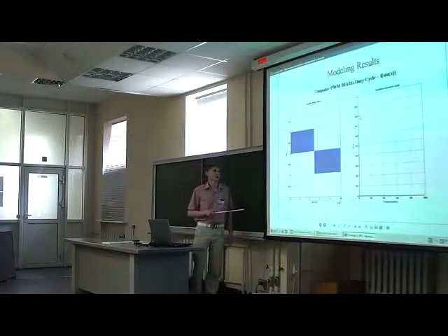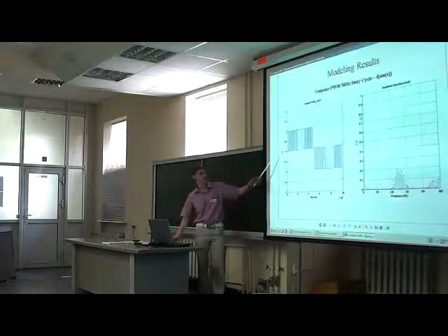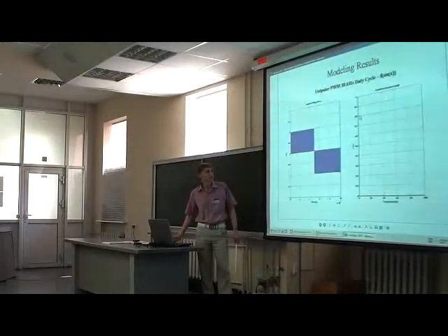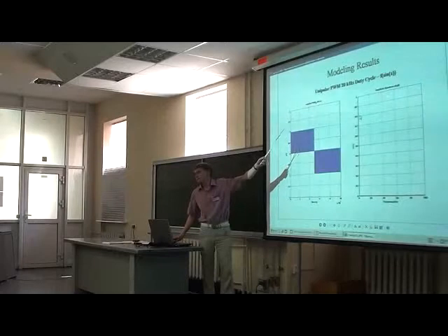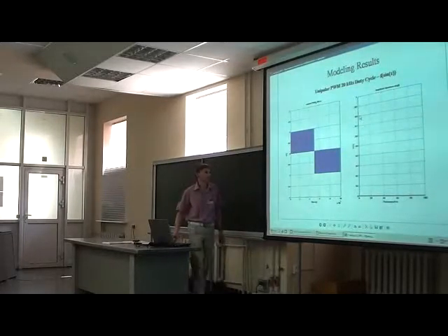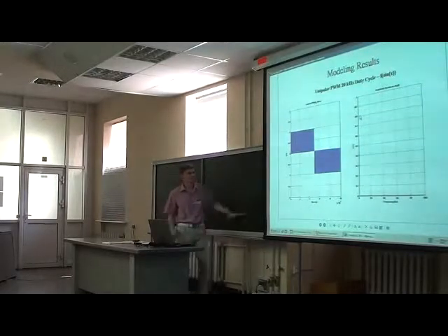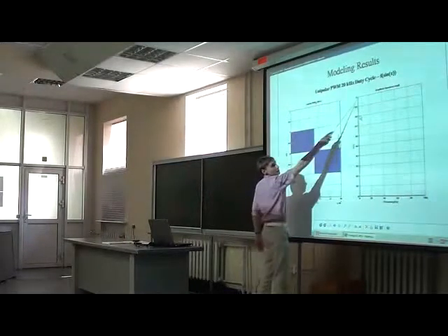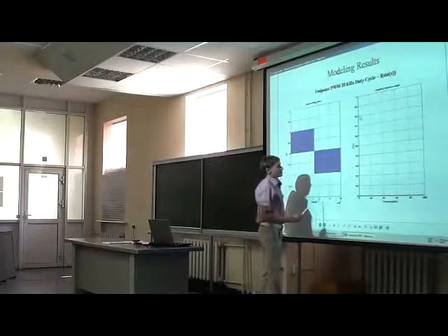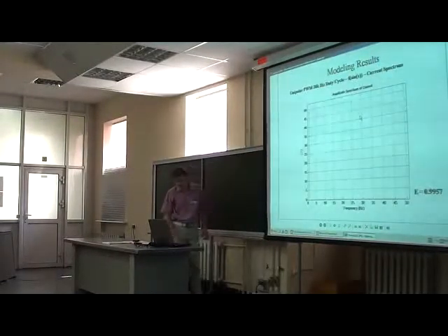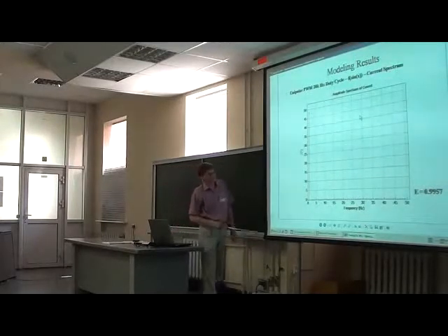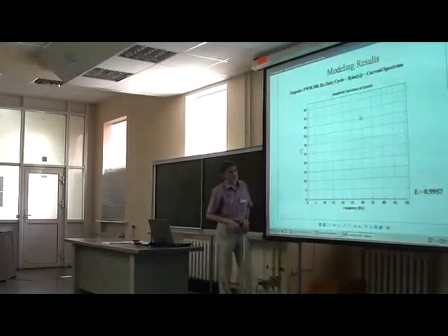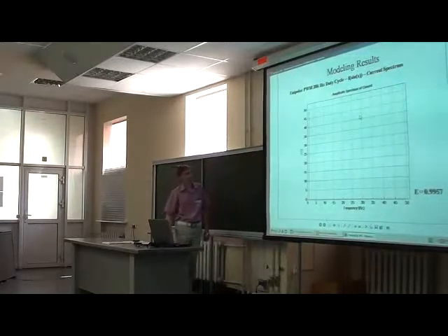And now, for example, it's also this signal, but PWM is not 50 Hz, but 20 kilohertz. It's really complicated to see this in this picture, but here we see that we have only one harmonic, and it's very big. In this example, we have energy efficiency 0.9957.